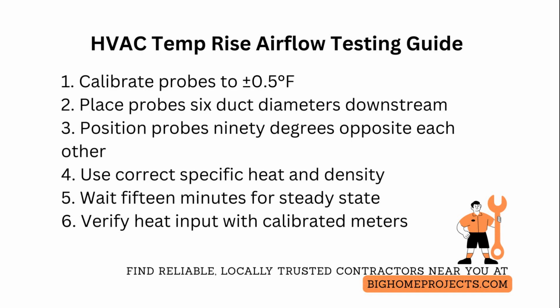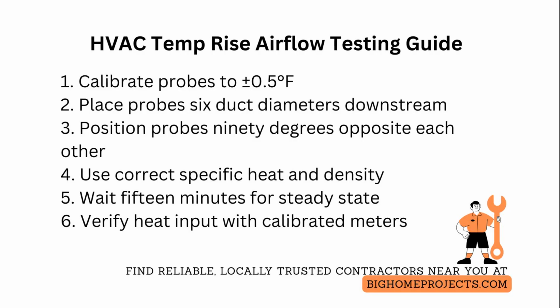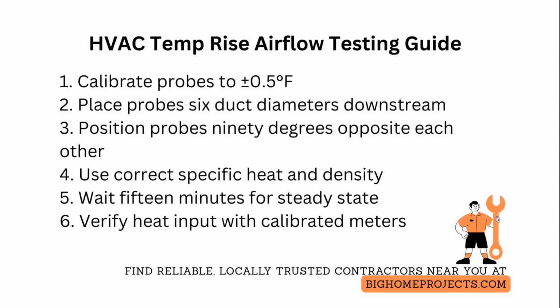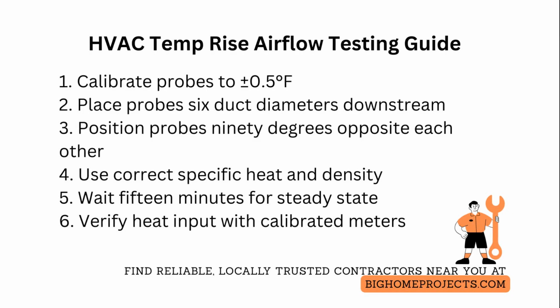Log all raw readings, timestamps, probe serial numbers, and ambient conditions so any discrepancy can be traced. This audit trail is what separates senior technicians from novices. Finally, if probe matching and ambient equality cannot be achieved, postpone the test until sensors are fixed because a small bias in starting temperatures propagates directly into cubic feet per minute error and can lead to oversized corrective actions.